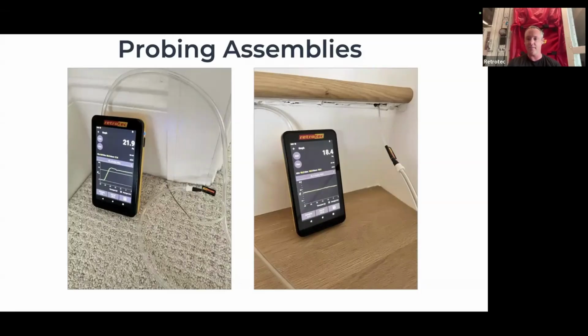So here, this is the same house that was having high energy bills. They were having high humidity problems in the summer and the shoulder seasons. I took these pictures before the Solo came out. The Solo manometer would actually be perfect for this. That way you don't have to use a whole other expensive dual channel manometer. But yeah, you could use that if you wanted to and just reference one of the channels. But yeah, the Solo is just kind of the perfect sidekick to have for something like this. So let's start with this picture on the left. What I'm doing is I'm taking that probe and I've just kind of wedged it in there to get up underneath that baseboard between the carpet.